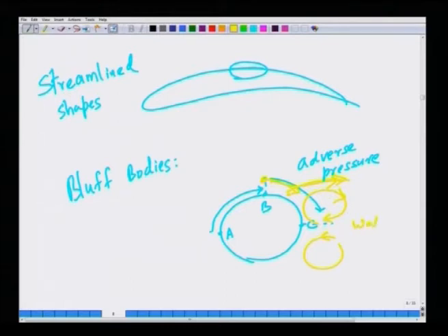This is called the wake, and the boundary layer theory fails here because the viscous effects are no longer confined only to a small region close to the solid surface. It is actually a very macroscopic region comparable to the size of the sphere or cylinder itself. Therefore, the simple boundary layer analysis that is designed to work for streamlined objects without separation does not work for bluff bodies.